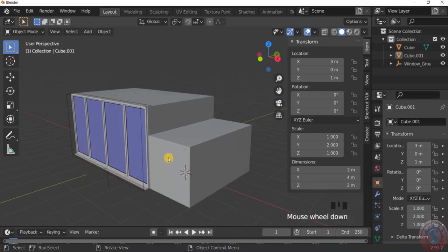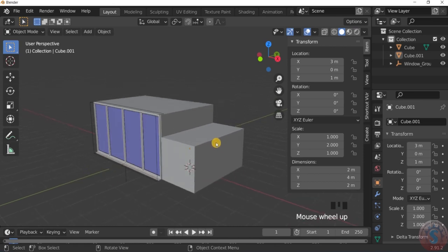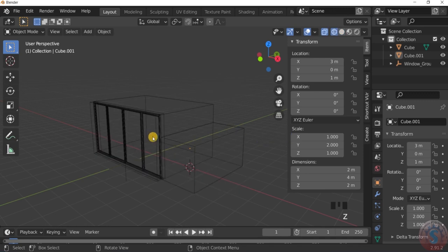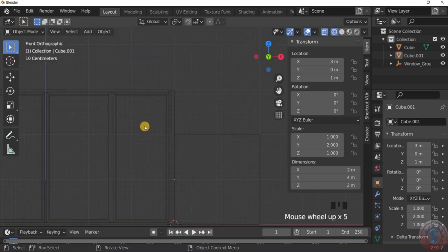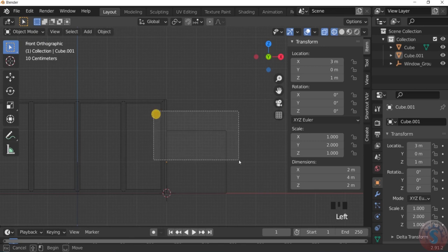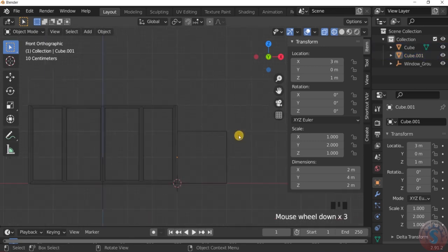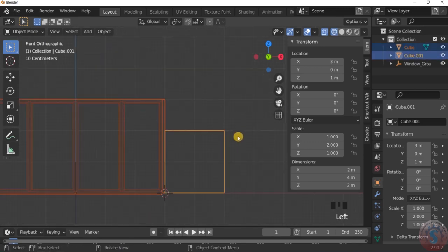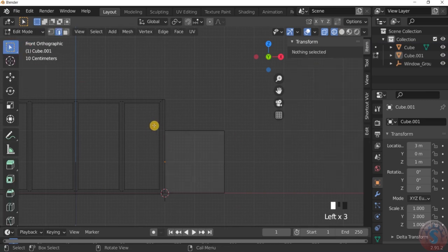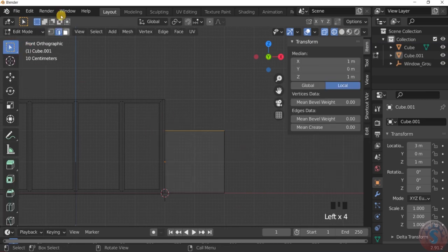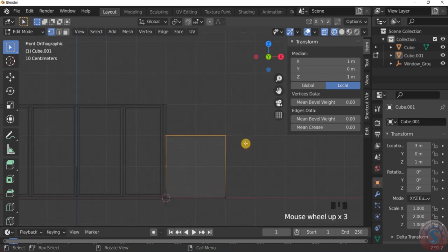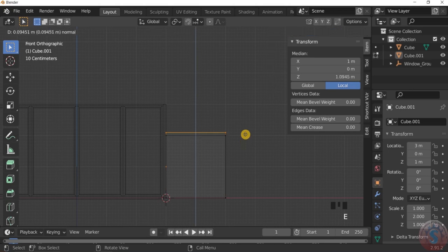What to do, I will show you. After creating the cube, go into Z and the wireframe and go into 1. You want to extrude this, so click on the edit mode and select the vertices here and give the extrude option.